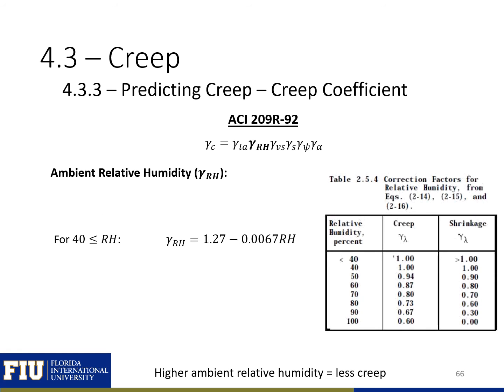The next factor we have here is the factor that takes into account the ambient relative humidity. If we have a relative humidity greater than 40%, we can use this expression. And we can see that a higher relative humidity will lead to less creep.